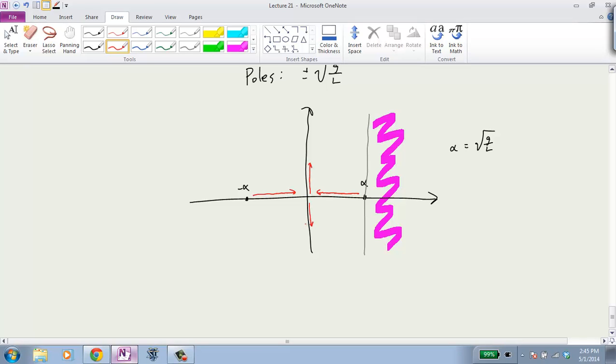So can we make the system stable with this kind of feedback? It's never going to be stable. It'll be almost stable, right? So let's do that. I'm doing this because they have a max angle. It'll shut off if it goes too far to the side. Okay, so that's pretty good, actually, right? So it turns out that the friction in the system actually helps you slightly. So our theory was saying that it won't be stable, but it'll be really close to being stable.